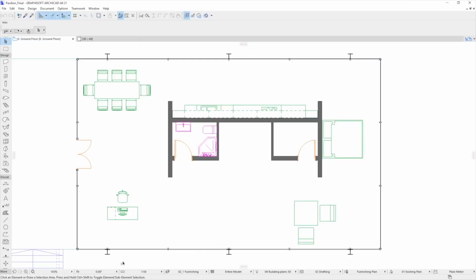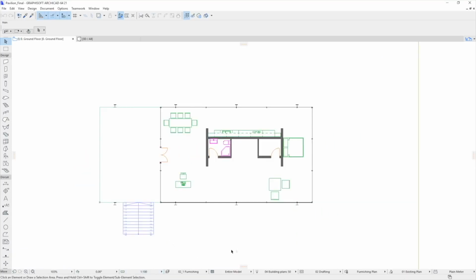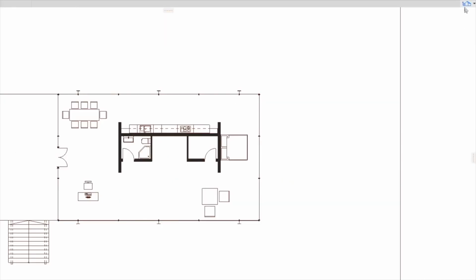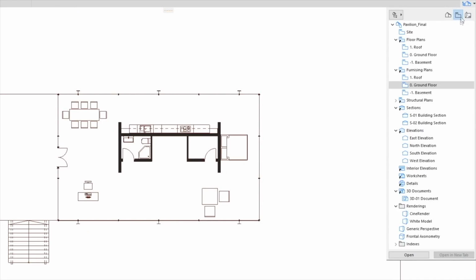A view is defined by these factors, plus the current zoom, the dimensions, and some other factors. At the Quick Options bar at the bottom of the screen, you can change these settings for the current project representation. Click on any of the buttons and see what changes occur on the floor plan when the settings are changed. Note that the current Quick Options settings are not saved to the views automatically. To do this, you must open the View Settings dialog.